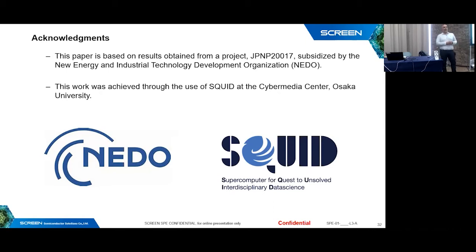Try the main assumption: to just not have a turbulence model, just set it to laminar. Let's try. I mean, we can try. We are open to suggestions, but definitely it works. So you can see that the flow is not laminar. You see the wave. You see the flow is not laminar at all. We think it's because of the wave.